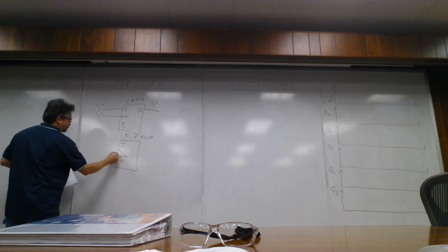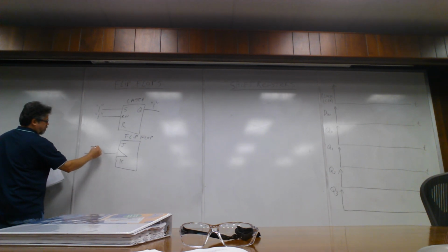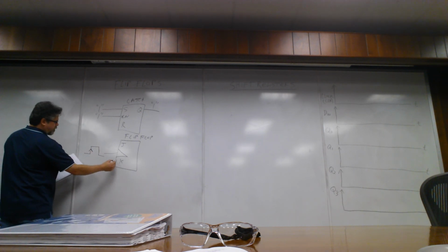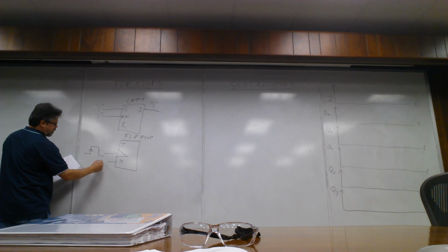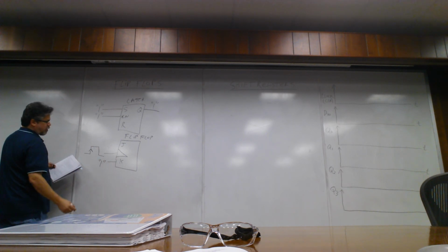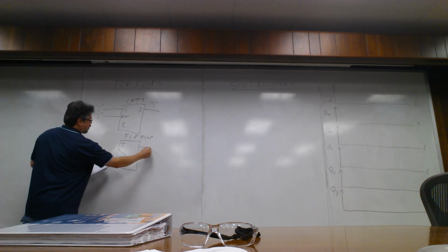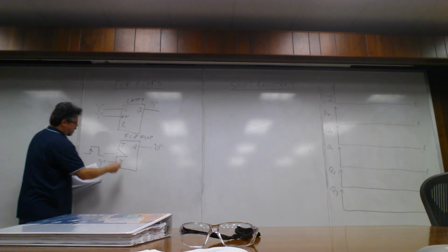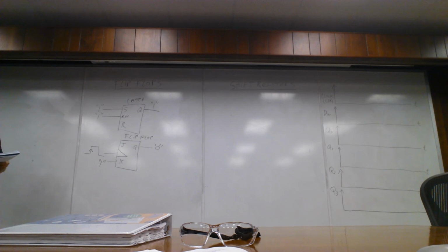So if we have a clock pulse like this, and we're looking specifically at the rising edge, there's no bubble here. So if we say, in this instance, 1 here for K, for Q we're going to have a 0 output because we reset the flip-flop.